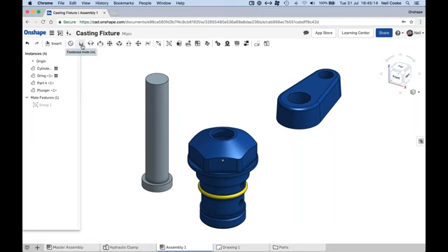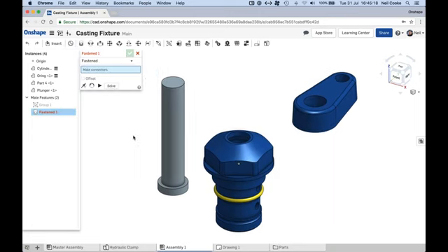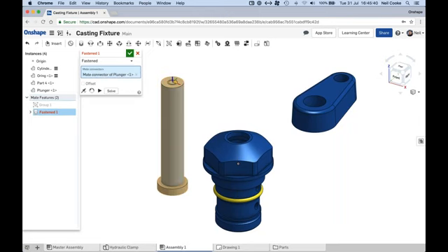But essentially, if you want to fasten 2 parts together, you click the fasten mate, and as you hover over geometry, you'll see that this little symbol appears, and this thing is called a mate connector. Think of it like a coordinate system, where the red, green, and blue is X, Y, and Z, and obviously the orientation of this particular one is pointing up. So you say, okay, I want to connect this coordinate system. Well, it's mate connector really. And then as you hover over any other geometry, you can see that these appear.